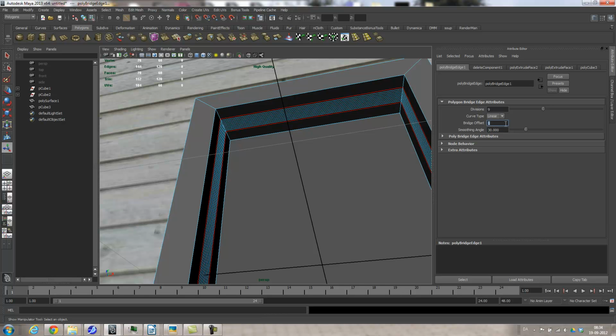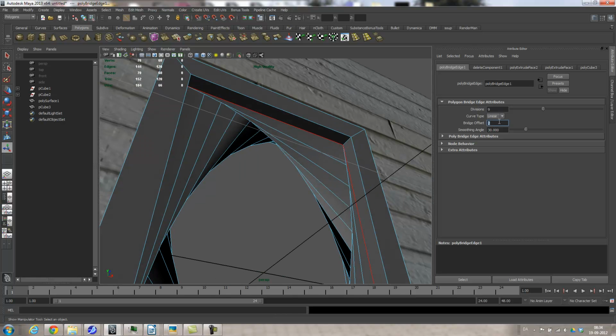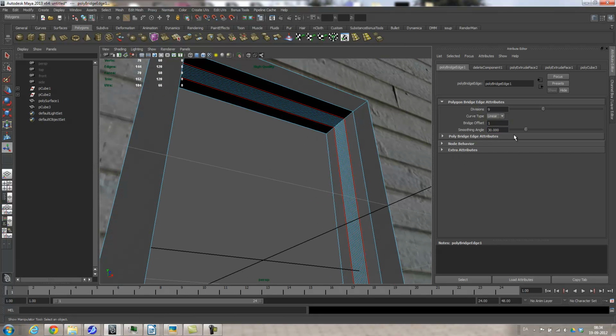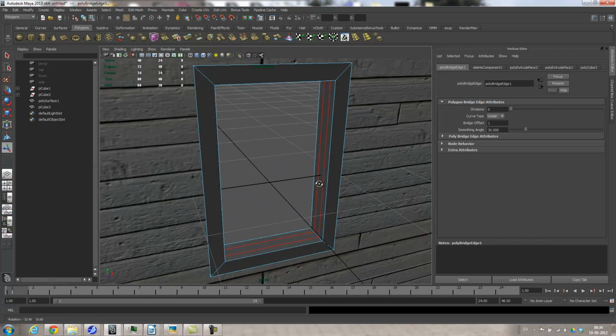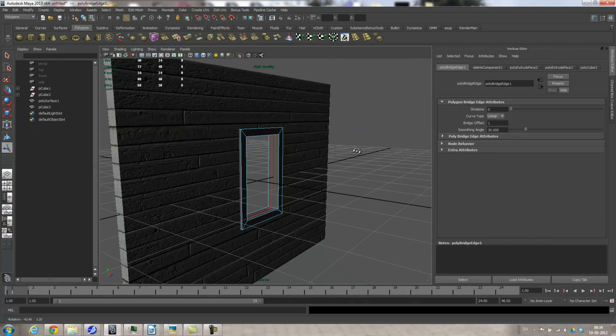So if this is offset a certain amount, it will twist it. If you have the edges across, and it starts and connects this to this, you'll get a warp. So when you do the offset, it will use this one instead. Usually this is just done by testing it, typing in numbers. So in this case it needs to be 1, and then I should just set the divisions low. That's a little more technical than it had to be. We could also just have deleted the backside and we'd have no problems.